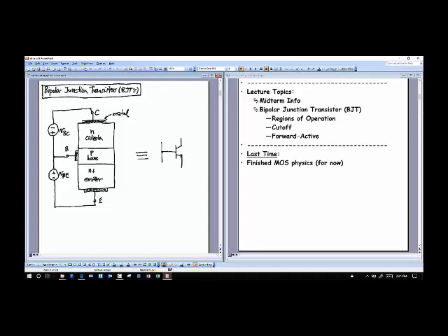Okay, and so I'm going to have a base terminal here, a collector terminal up there, and the emitter terminal, where you can see that the emitter terminal is where the arrow is. And for an NPN transistor, which is what this is, the emitter arrow goes out and down in this symbol. I'm showing you that because later on I'm going to show a PNP device. And so in this I could put my same voltages here, plus minus VBC, close that up there, plus minus VBE, close that up here.